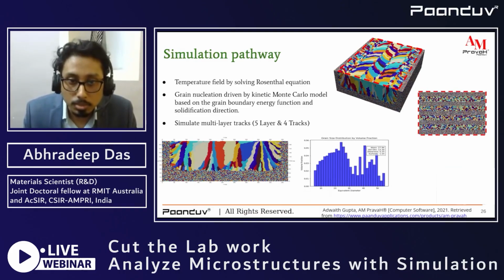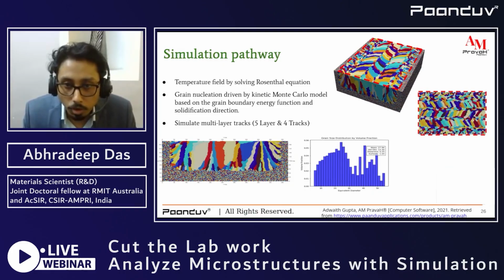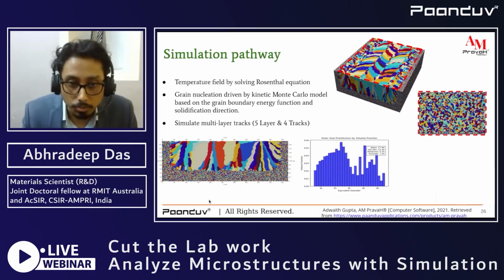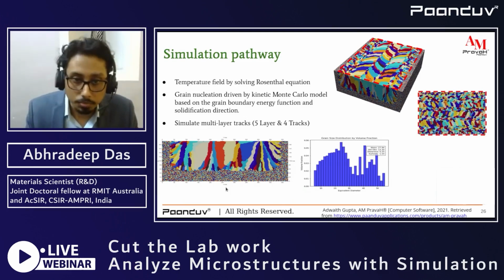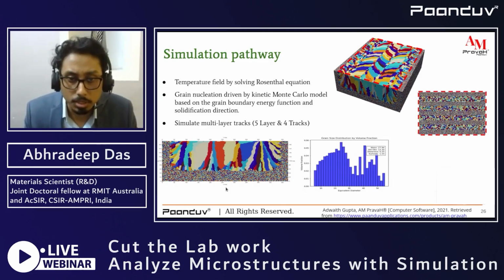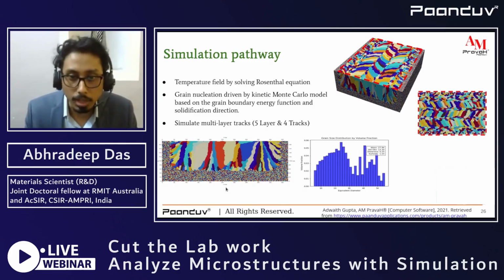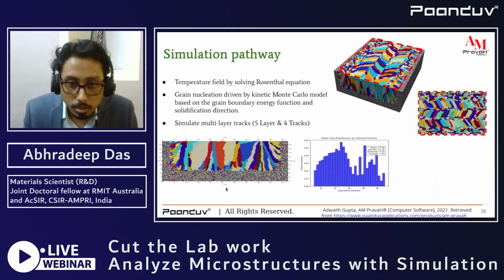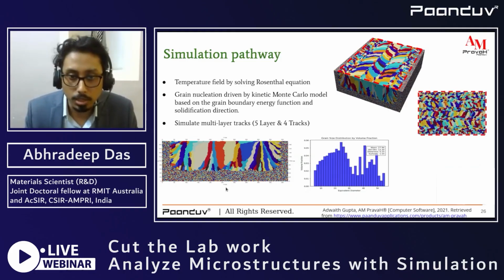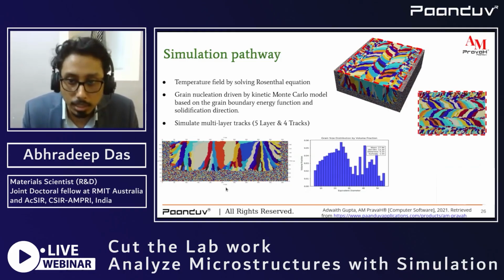We can see some subgrains have formed in the front face of the meltpool structure. The microstructure developed here has a columnar front as well as some needle-like cellular prismatic structures that have some epitaxial nature.